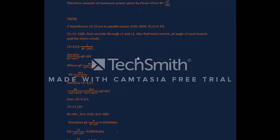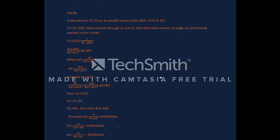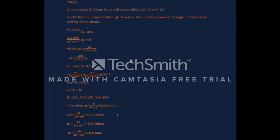Now we see the next question. This question says to find the two impedances Z1 and Z2 that are in parallel across 25 Hz, 100 volts. Z1 is given and Z2 is given, and it asks us to find currents through Z1 and Z2, and also the total current and PF of each branch and the entire circuit. So let's take admittance Y1 = 1/Z1 = 1 upon the given expression, and this is the second expression.